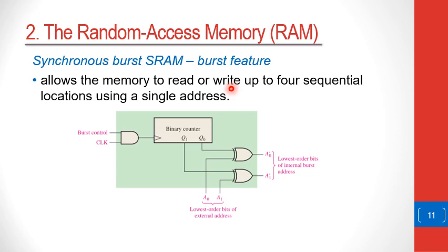So when the memory is addressed with a single address, the burst feature allows that address to read the next 4, in fact the adjacent 4 addresses sequentially, even though only one input address has been placed onto the address bus.